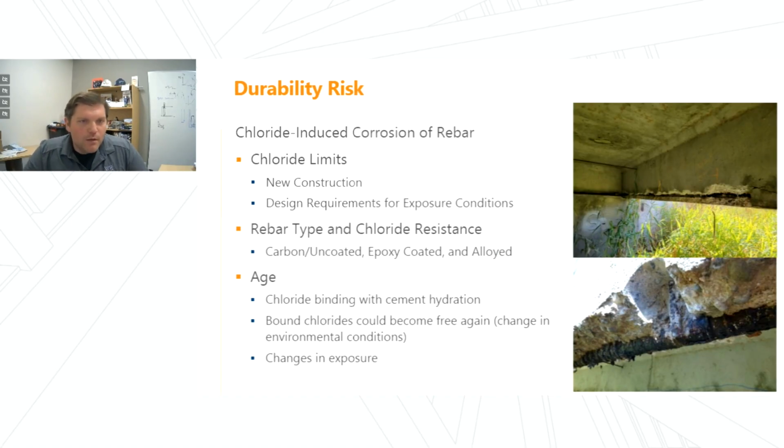So what does that mean? Chloride-induced corrosion of our reinforcement, as we talked about, is common and detrimental. And how do we mitigate that risk to durability of our reinforced concrete structures? Well, for starters, we can limit the amount of new chlorides that can be present in new construction, so limiting the amount of chlorides in any of the constituent materials in our new structures.